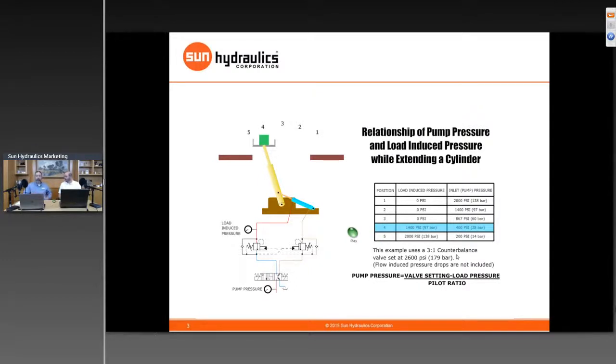Yes. So that begs the question then, are all the counterbalance valves that we have, can we just easily replace one for another? You can typically find a different functional type that will fit into the same cavity. With some of the new products, the load match and the load adaptive, the family lines haven't been completely fleshed out yet. Give us a little bit of time, check back often, but typically, yes, if you have a T11A cavity, we will have a standard counterbalance valve that will fit that, we'll have a load control valve that will fit that, and we will also have load match and load adaptive valves that will all fit into the same cavity without you having to redesign the circuit. So generally the same cavity, but we could put in one of 4 different families of valves. Correct. Okay, nice to know.